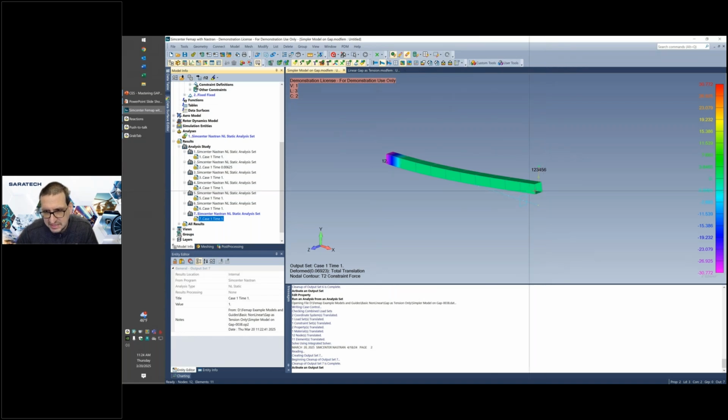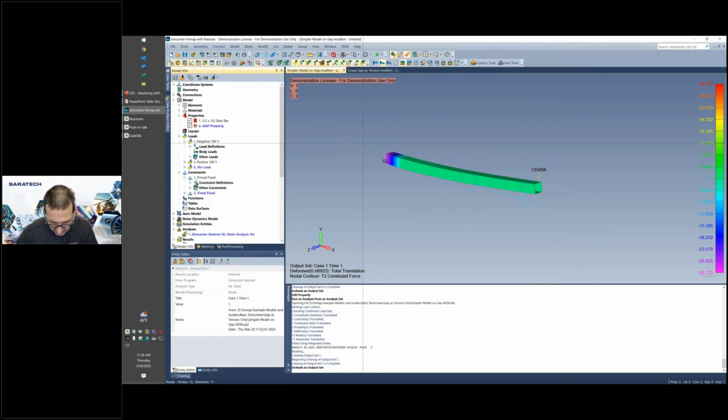So you can always fix that by doing a little bit of math, calculating what additional, if you just do a linear assumption, like if no spring force versus the deflection here, find the deflection, and then find out what your actual final force was. You can always work backwards there to find out what kind of initial gap you'll need to get that final preload force that you're actually looking for.